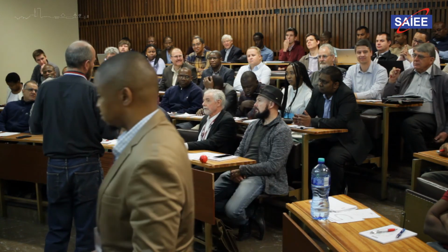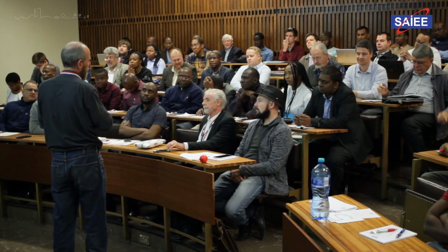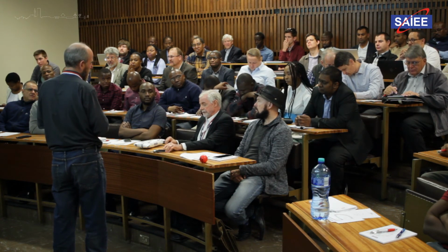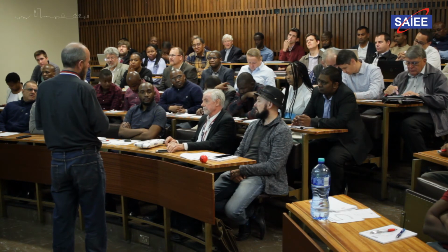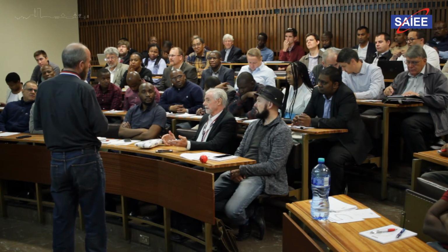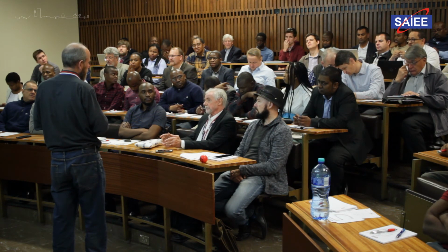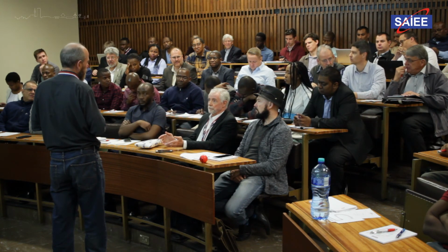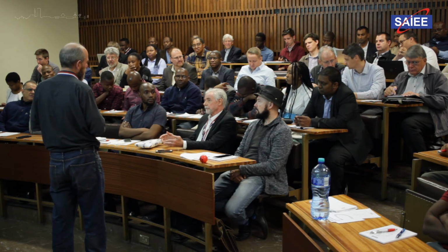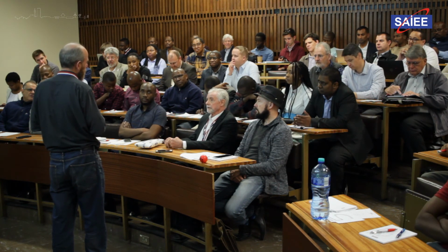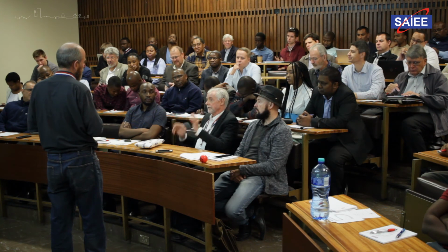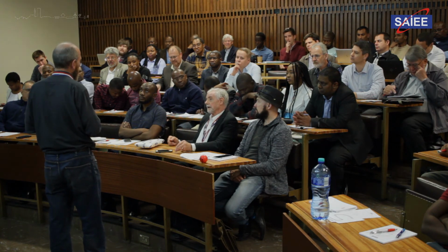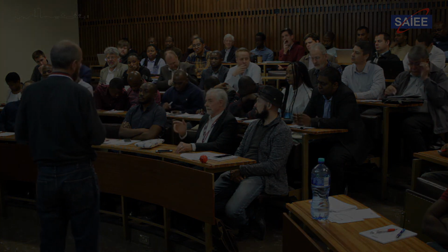So it has to do with the densification, in urban versus maybe deep rural. I don't know any answer to that. You just have to look at trends in the area. Because not each of the backyard shacks is going to equal the same, so you might say, look, the normal place there says 1.5 kVA. I know that some of them are using instead of 1.5, a 4 kVA load, and then just design for that, and say, look, hopefully we get saturation. You can't put a lot of appliances in there anyway. But it's not exact science at all.